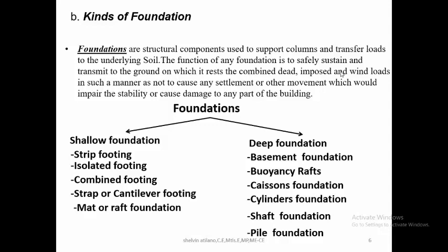The function of any foundation is to safely sustain and transmit to the ground on which it rests the combined dead, impulse, and wind load in such a manner as not to cause any settlement or other movement which would impair the stability or cause damage to any part of the building. So if you look at it, that is the scenario. It's always like that. Loads are always transferred from top to bottom and going to the soil.